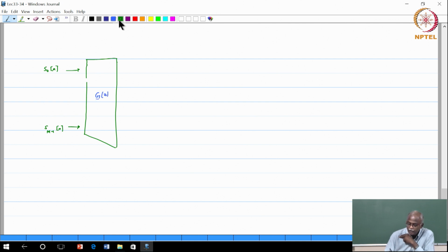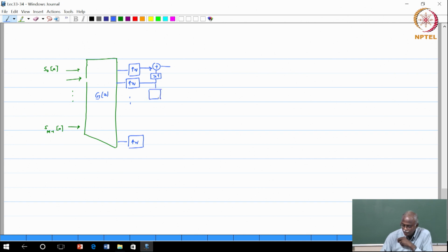Basically all these polynomials that were G of z to the n have become G of z, and on the right hand side we have the upsamplers, upsampling by a factor of n, upsampling by a factor of n, dot dot dot, upsampling by a factor of n, being combined through a delay chain of n units. Okay. Indicate the arrows so that there is no confusion.